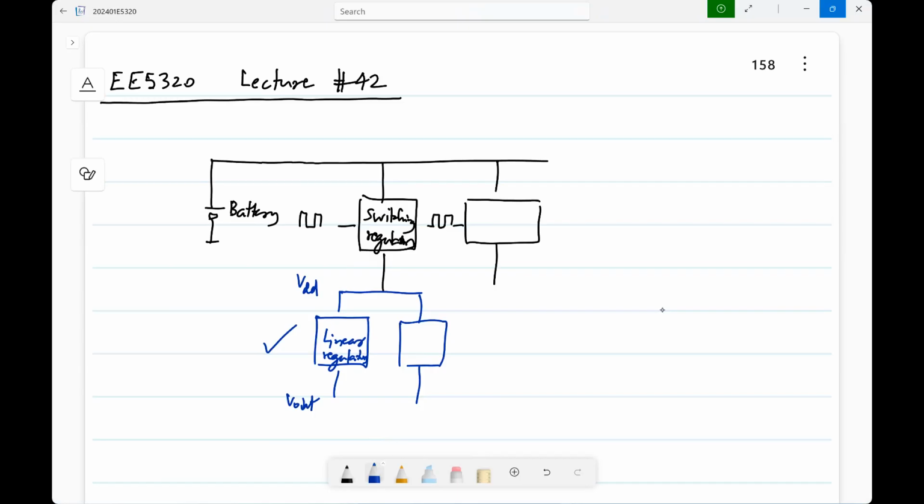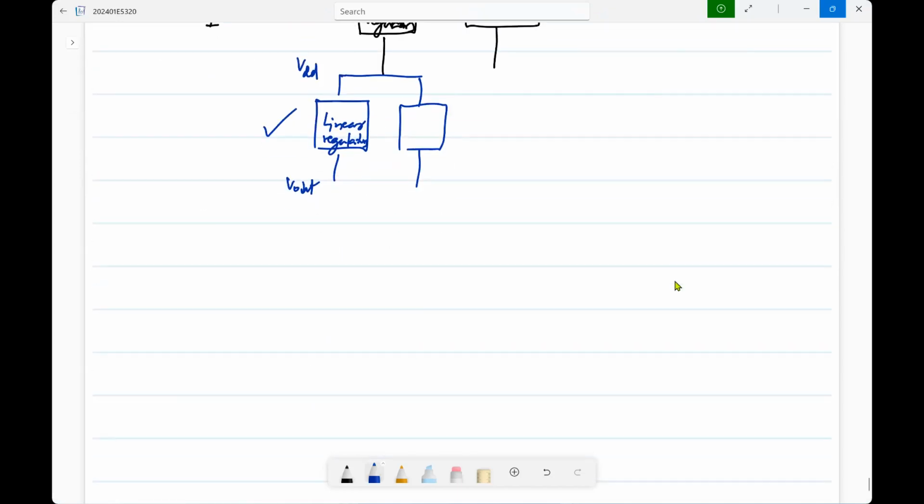So it does not quite operate in this small signal type regime where the effect of increments are small. Okay. Only thing is you still do the same linear analysis, but you do it for the minimum load current, maximum load current, somewhere in the middle and so on, make sure it works. Okay. So we saw that with this constraint, so let's say we wanted a 4.8 volts output, you start with a 1.2 volts